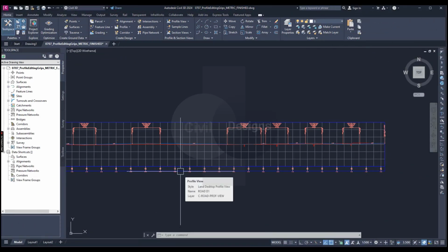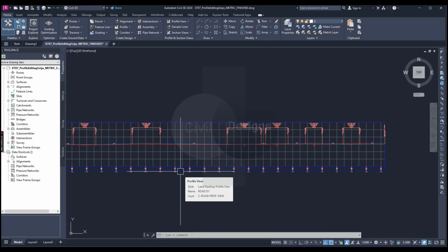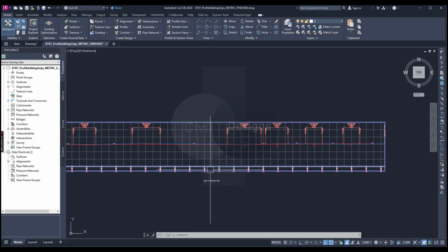Hi students, we are going to edit profiles using profile layout tools in this exercise. Beyond the simple grip edits, but before changing out the component of typical profiles, we can modify the values that generate an individual component. So in this exercise we will use the profile layout parameter dialog to modify the curve on your design profile. So just open your drawing